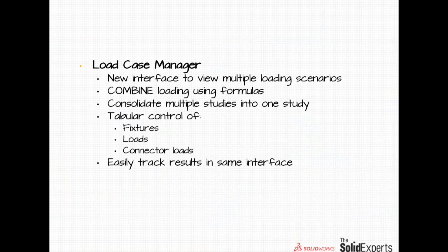This makes it very, very simple to set up a large number of loading conditions in one easy-to-use table, as opposed to setting up multiple studies using tabs along the bottom of your screen, like we're all used to doing. Now it can all be managed in the same table in one study. There are multiple filters as well for focusing just on different options like the fixtures, loads, and connector loads. This is all managed in the same interface.